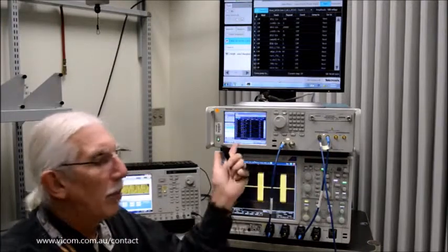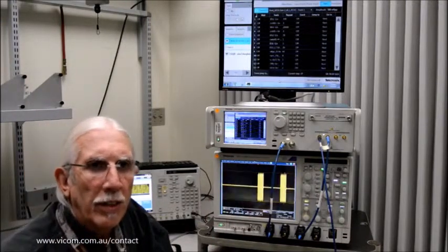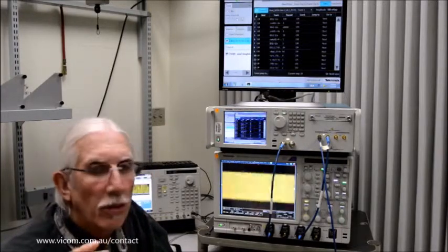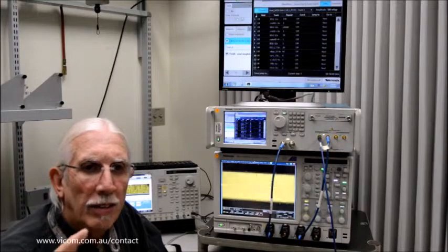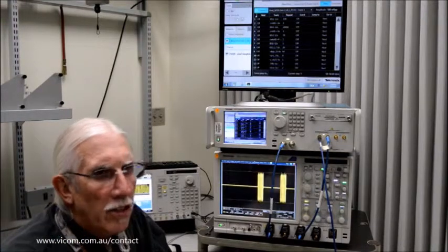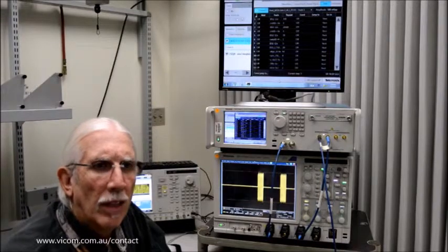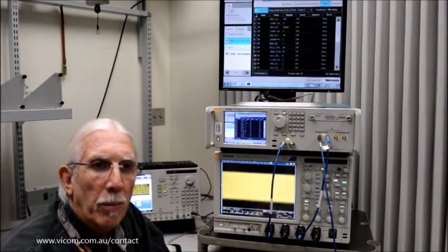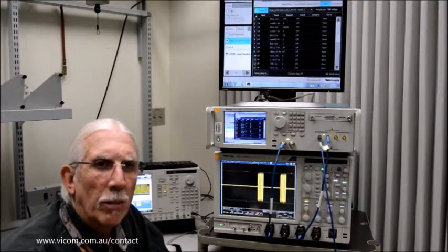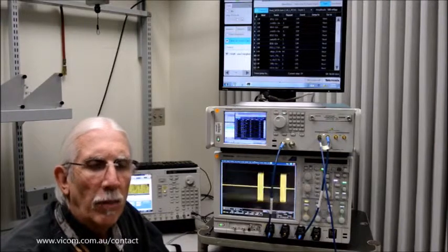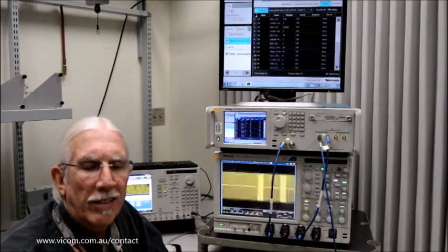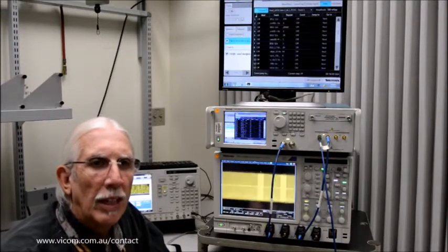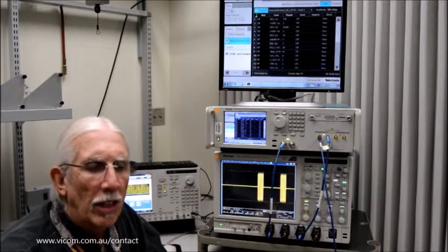Here I've loaded a little bit more complex waveforms. In this case, it's a serial data application where the first part of the sequence is used for putting the DUT, or the device, into a loopback mode, and then actually running waveforms that have the jitter content provided so that you can make sure that the device works in compliance conditions, where you have to add a certain amount of jitter, a certain amount of ISI, a certain amount of random jitter, and then combine it all into the waveforms and test it and make sure you don't get any bit error rates.